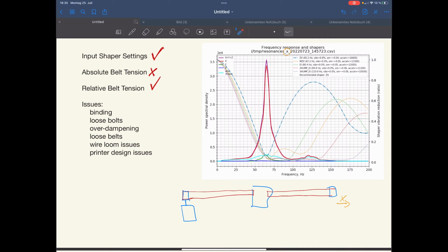Hey, this is future me helping out my past me in the explanation, because maybe it wasn't clear enough what is actually shown. The printhead is probed for all different frequencies during the measurement, and we look at the reaction, and the more it reacts, the closer it is to the resonance frequency. And this is what we can see here. The higher the peak, the more it reacts to the specific frequency.